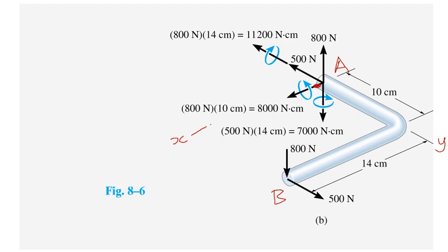Therefore, if you look carefully, now this 800 newtons is shear, and this point here is right at the neutral axis, right? So if we have a circle, then we have the x-axis here, so here is X. Then that is the Z axis up there, and we are looking from Y, right? Y is the center here. So we are looking from the Y axis. So 800 newtons is going in the Z direction. Therefore, point A is at the neutral axis. So if we take this as the shear force, point A will experience the maximum shear stress.